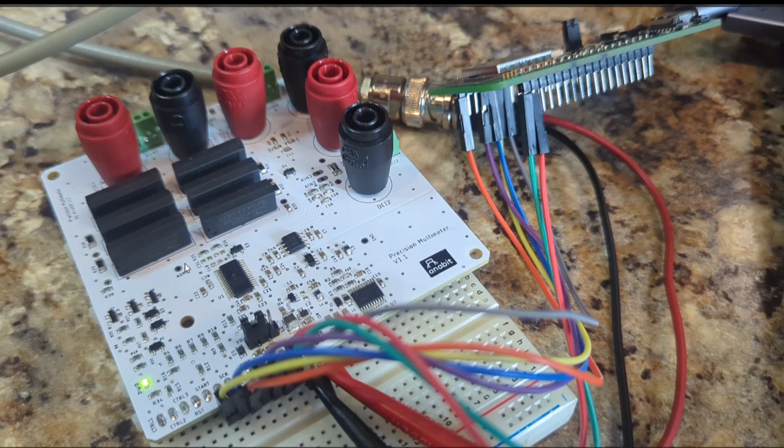It can measure voltage between 200 volts and negative 200 volts, plus or minus, DC or AC. It can measure resistance real accurately, but it can also measure current real accurately. And this circuit right in here is actually the circuit we just looked at in our example for showing these sense connections. Here's the shunt, here's some test points, here's our filtering, and here's our amplifier and ADC.